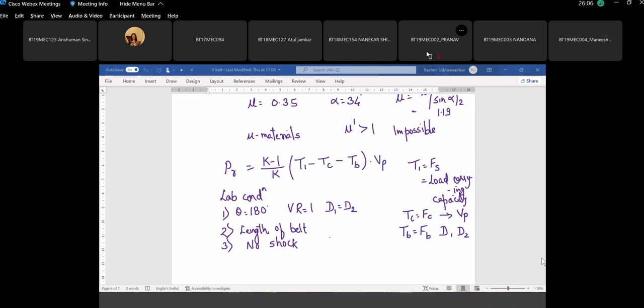Below that, you would get a speed ratio range d by d and the small diameter correction factor. I'll tell you how to use this table. Similarly, for the equivalent pitch diameter and belt speed, how to get the power rating in kilowatt. This also I'm going to discuss. Turn the pages.